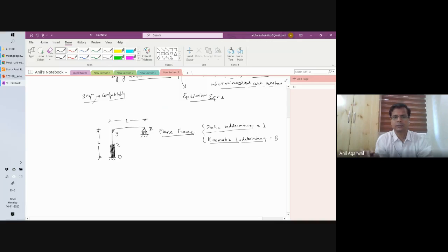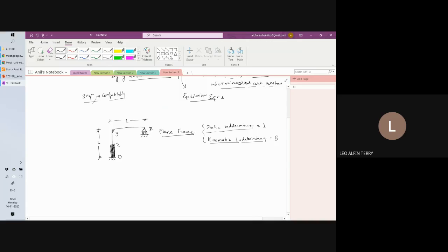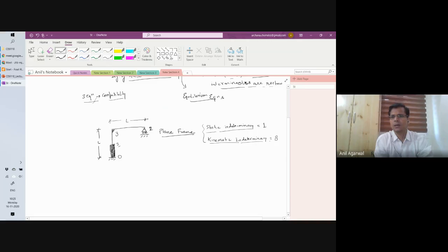So, that's what everybody is saying. I suppose everybody is in agreement with this. So these are, to be more precise, basically there are free degrees of freedom, FDOFs, and there are restrained degrees of freedom. So if I say restrained degrees of freedom, then there are 3 here, there is 1 here, so 4. Free degrees of freedom in this case are 3 plus 3 plus 2, 8. So total degrees of freedom, which we can just call DOF, are 12, isn't it? Agreed, right? Everybody agrees with this?